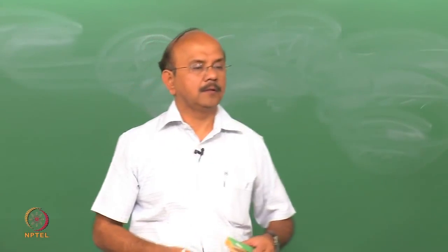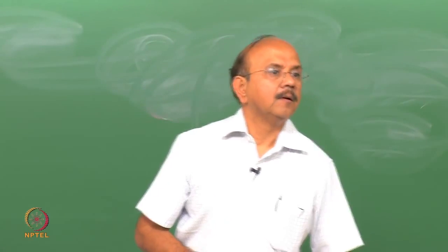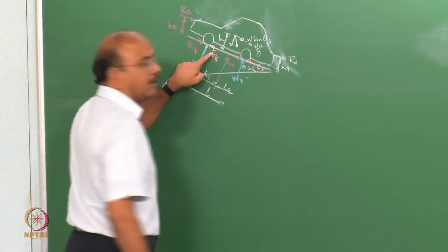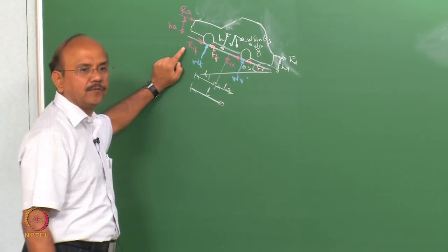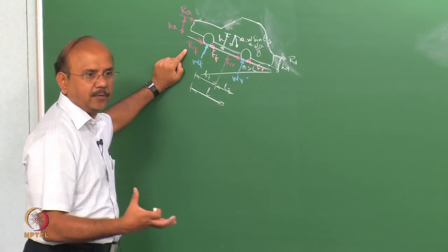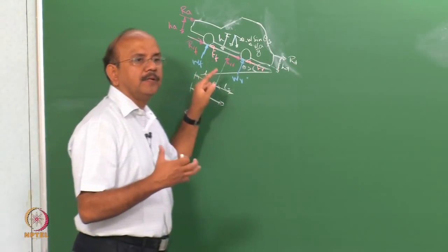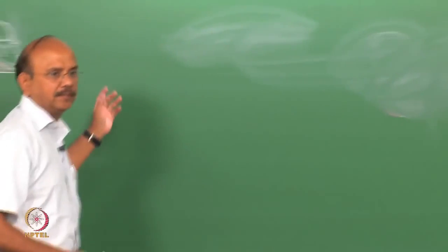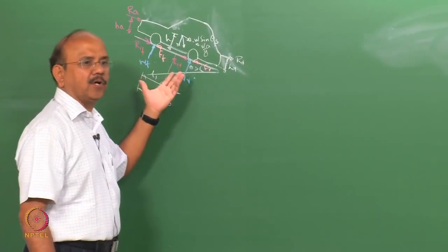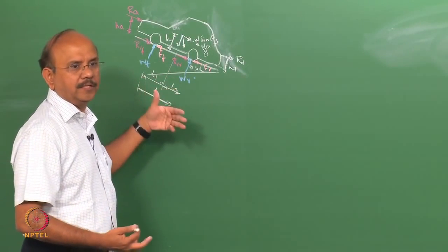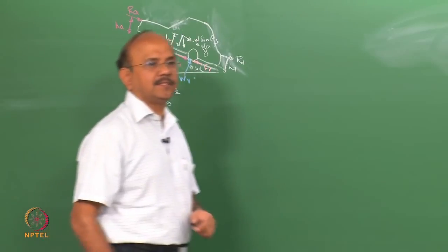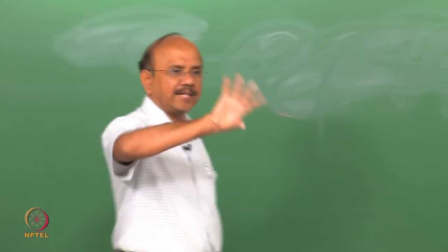So, what decides the direction in which you draw that rolling resistance component? What is the direction of this force? Okay, that's the question. Obviously, when I am giving a driving torque, the force is in this direction. If I am giving a braking torque, it will be in the opposite direction, right? Obviously, that's the thing. On the other hand, rolling resistance depends upon the direction of rolling.